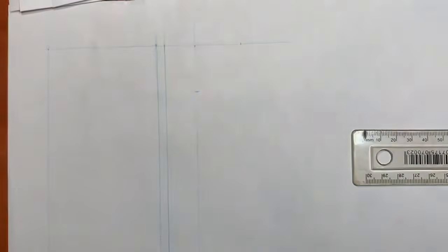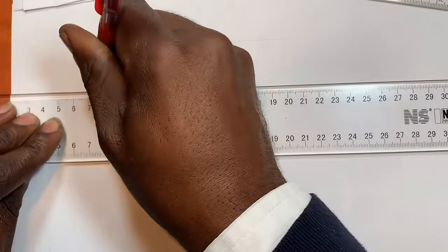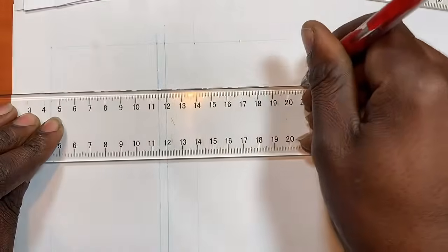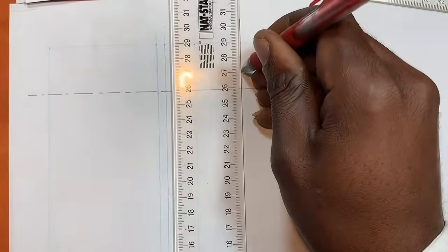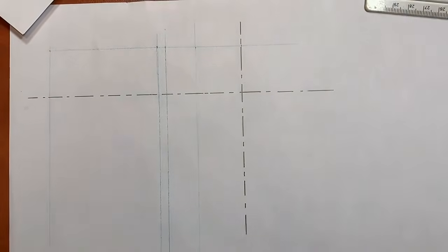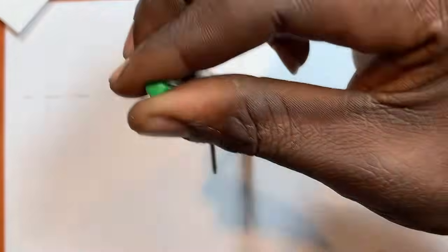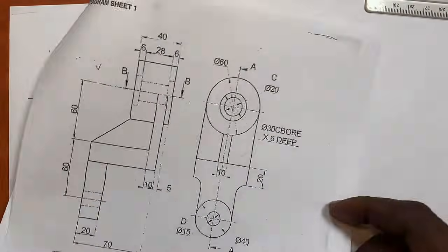So I simply open my drawing compass, I place it here, I mark and I mark. You understand? So on this one, it's going to give me the horizontal center line. I'm trying to be fast. The horizontal center line. Then on this one, I'm going to draw the vertical center line, shorter. The center line is supposed to be drawn like this. Okay, so now I can come and place my drawing compass right here. Then I draw this one, solid, dark. There you go.